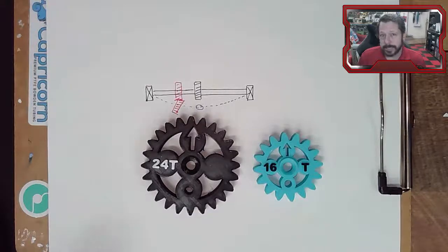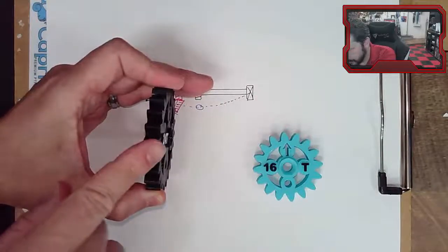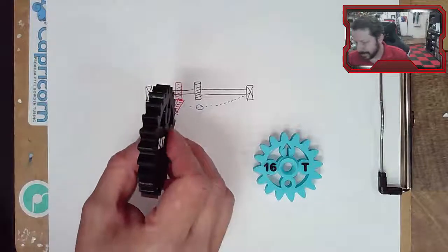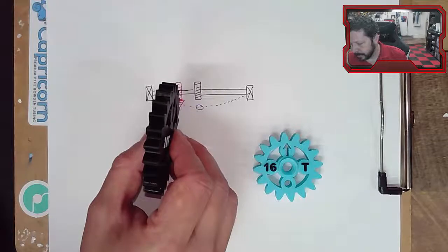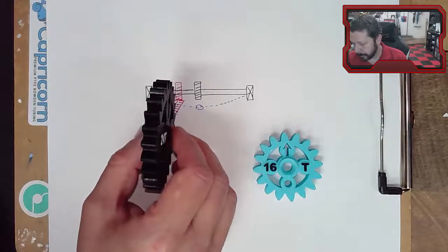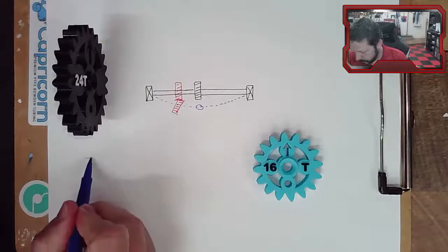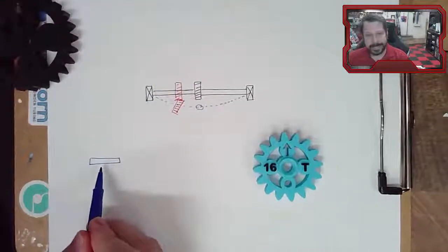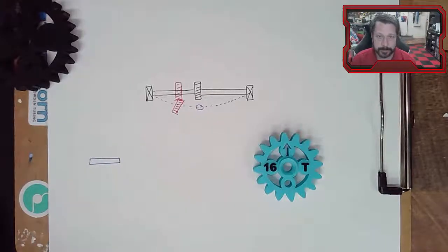There's herringbone that's kind of useful. So herringbone, instead of the gear tooth being straight across here, it's like in a little V shape. What that does is it keeps the gear from wandering left or right due to some kind of axial force on it. With straight gears, like this one, where the gear teeth come across here, maybe you need a little bit more surface area to reduce some pitting stress or bending stress.